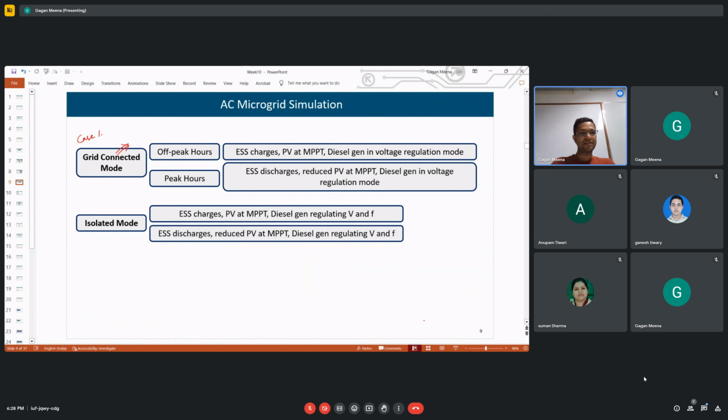And this new scheme which has been proposed, in this case what will happen? The utilization of fast will be more. The fast devices will be used at a higher frequency. They will be utilized much more than the slower ones. So that utilization ratio is not good. So they want to make it balanced. Slow should also provide, fast should also. Both of them should be able to provide a similar share of the reactive power requirement.